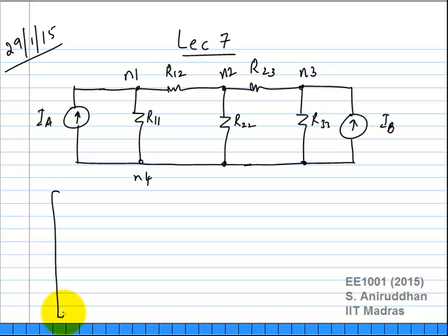Okay, so what is the first term? What was the form we want to write this in? We want a conductance matrix, okay, times a voltage vector, which is the variable vector, is equal to a current vector, which is the set of independent current sources, right? So the circuit we are looking at consists of resistors and independent current sources so far. That is really the easiest case, okay?